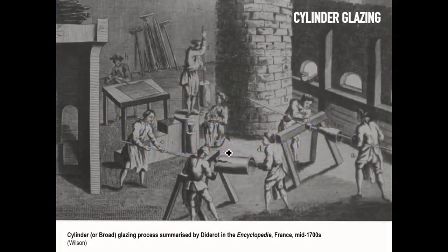But the process we're describing here is still blown glass, where the first steps are very similar to crown: glass is gathered from the furnace and blown, but instead of being blown to a sphere that is then opened up, cut, or reduced to a disc, the glass is blown into a cylindrical shape that is then cut along its length. You can see here the cutting operation happening. Then this cylinder is opened up into a larger sheet than crown glass, and used for window panels that can be fairly larger than crown glazing.